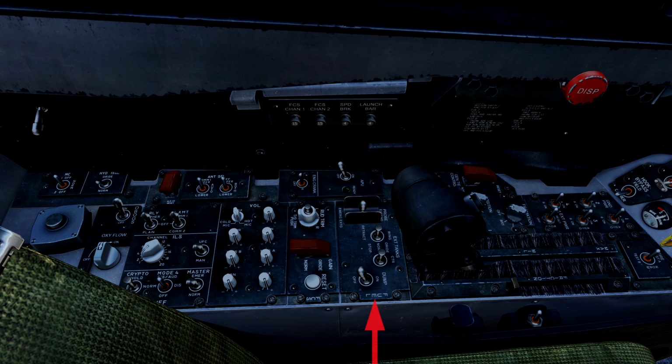So moving forward on the left console, we have the fuel panel, and on the left side we have the switch that controls the extension and retraction of the aerial refueling probe. And next to that we have two switches that control the fuel flow from external fuel tanks. One switch for the two wing tanks, and then one switch for the center tank. And again, normally these would be set to the normal position. And on the right side of the panel, you have your fuel dump switch, which can be quite important when you're bringing the aircraft back to the carrier and you have to make sure that you're within your maximum trap weight.